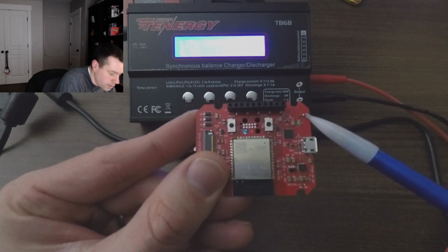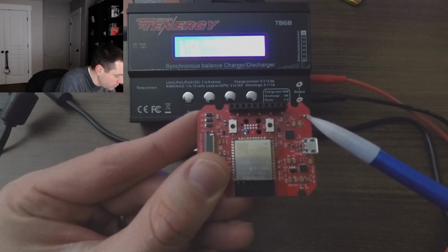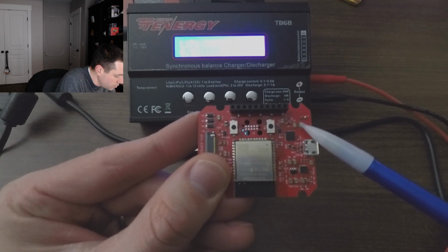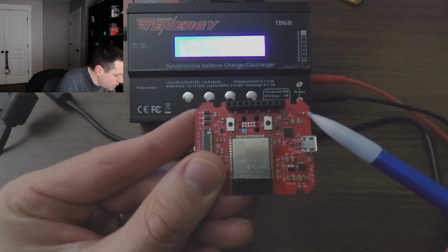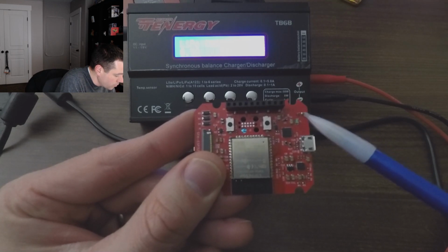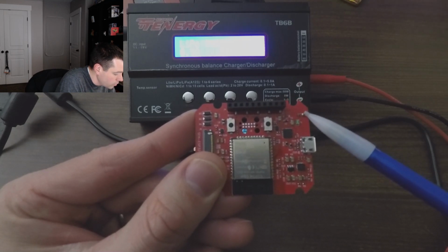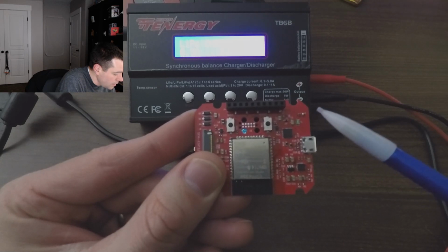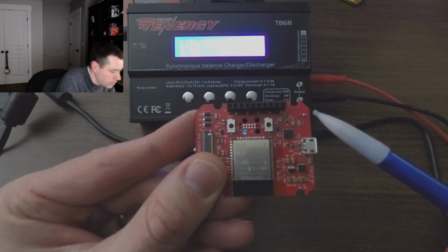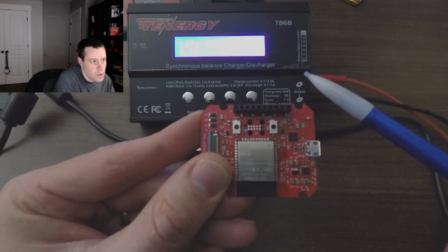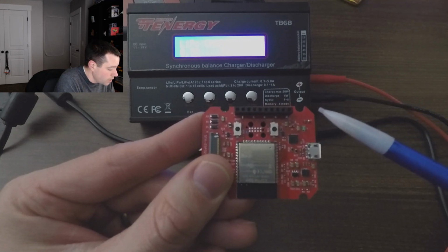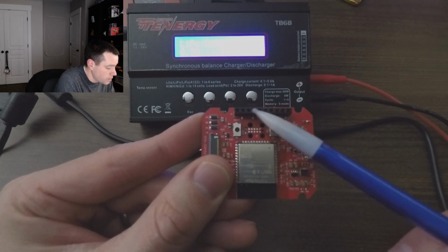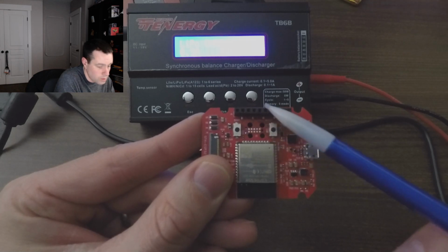This is the battery right here, and this outside pin is the positive. The inside pin is the, do I have that right? Yeah, negative. And so I could solder a little wire from right here. That'll give me the battery voltage, and I need it to voltage divide. So I could bridge that off into a little breadboard, divide it down, and then come back into one of the pins up here, and then read that through firmware.